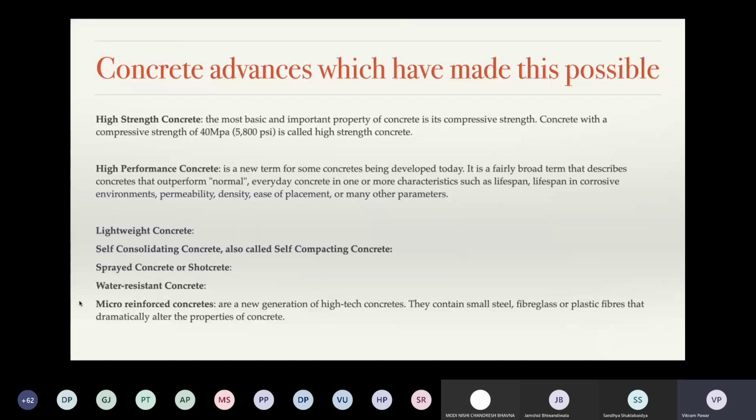If you are having M20 or M15 or M10 grade concrete, then these kinds of pressures will easily crumble the concrete. The amount of pressure that you are applying in either post-tensioning or pre-tensioning is quite intensive. It will be as much as the pressure which is going to come vertically down through gravity. Because of which you need a high strength concrete.